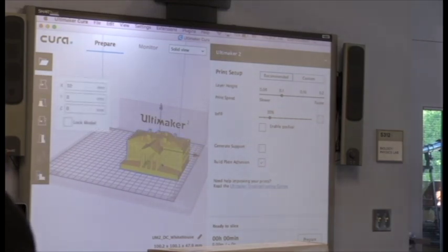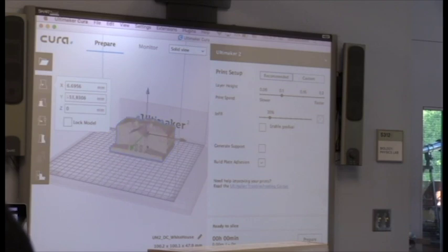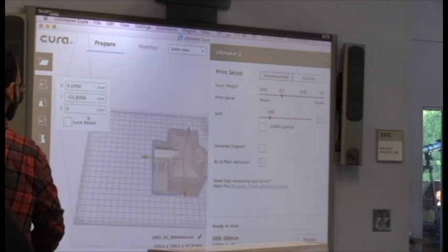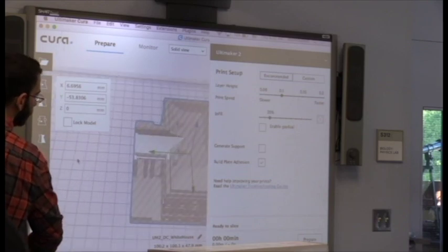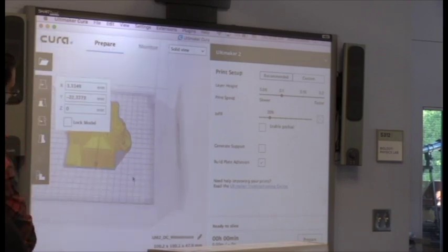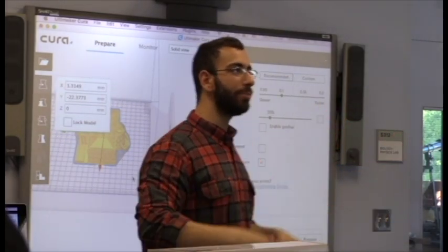And I honestly usually never use these dimensions up here. You can just grab these arrows and pull on them in whichever direction you want to go, and you can pull onto the front. You see when it's grayed out? That means, when you look at it, it's exceeding. See, if we go in the back, this little gray area, it can't be in there. There's a little hair that's in there. That's not good. Whenever you see hatchings on it, that means you're out of your perimeter. It can't print into there.